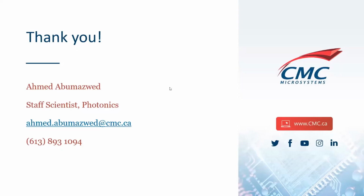In fact, I believe this is what our MATLAB example is using. So you don't necessarily need to link MATLAB from the user interface. You could just use MATLAB to generate whatever netlist you want, call OptiSPICE, run your simulation, and then load your results back into MATLAB and continue your processing. In fact, we have done this kind of example before for running Monte Carlo analysis. Okay.